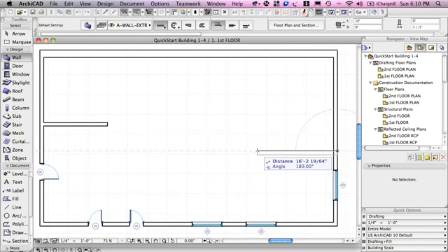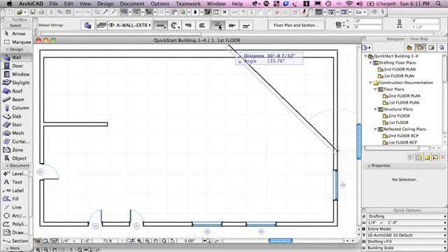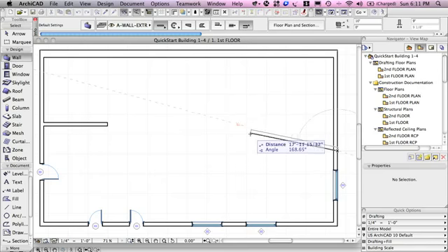However, sometimes I would like to have that wall go the other side of my cursor, and this can be controlled using the construction options here, where I can choose left, center, or right, and I can switch this right on the fly. So I'll switch from the current one that's highlighted, which is this one on the left, and I'll switch to the opposing one, and you'll see as soon as I move back into the screen that the thickness of the wall now is above.